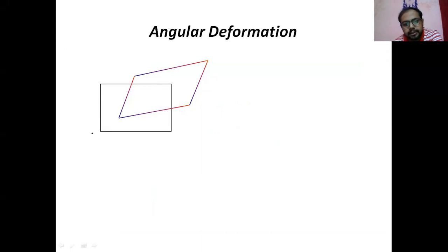So what is the fluid element? We are choosing A, B, C. The one rectangular fluid element we are choosing at time t, at any instant of time. So after delta t time, you see the fluid element as it is under continuous deformation. As shear stress is acting over it, it becomes in this way, in this manner.